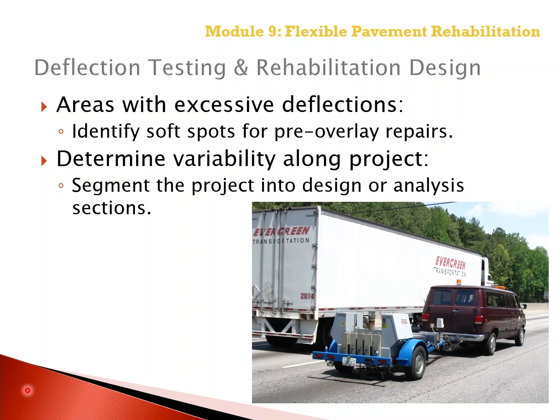However, using deflection data to segment the project into pavements with similar pavement responses in terms of deflection basins, we can determine better or more applicable rehabilitation design strategies for a specific segment, and then determine the average input or average layer properties for each of the individual segments.